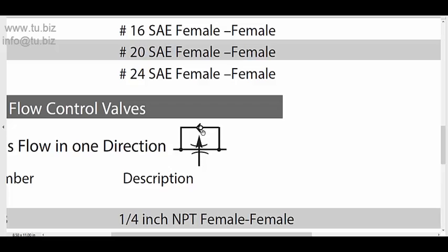It finds a check valve. The check valve has no restriction. You push it out this way, and there's no spring on the back of this valve, so the flow goes in this direction at very minimum pressure. So it's less pressure than going through the restriction of the flow control. So in this direction it's okay. It's like a free flow.